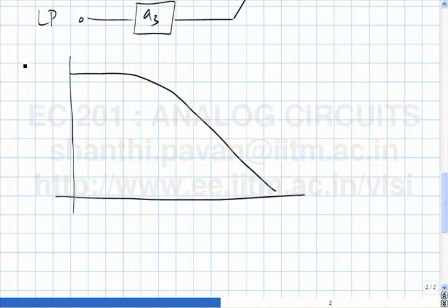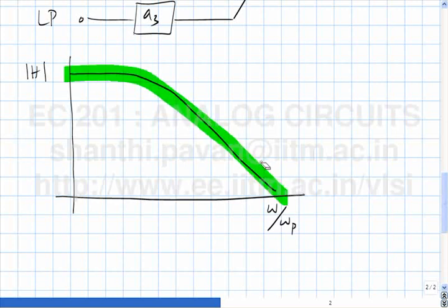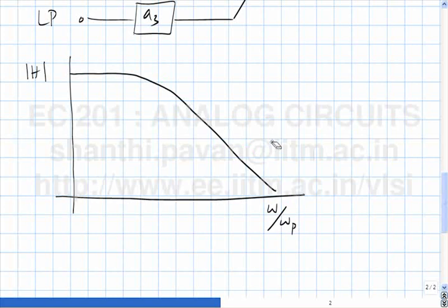How sharp the filter transfer function can change as a function of frequency is determined by the order of the transfer function. So with the second order transfer function, you probably just get some kind of gentle roll off like this. If you wanted a sharper transition, you would have to increase the order. So it might be something like this, and as the order becomes higher and higher, this transition band will become narrower and narrower. And how would you recommend that I try and realize the high order transfer function?